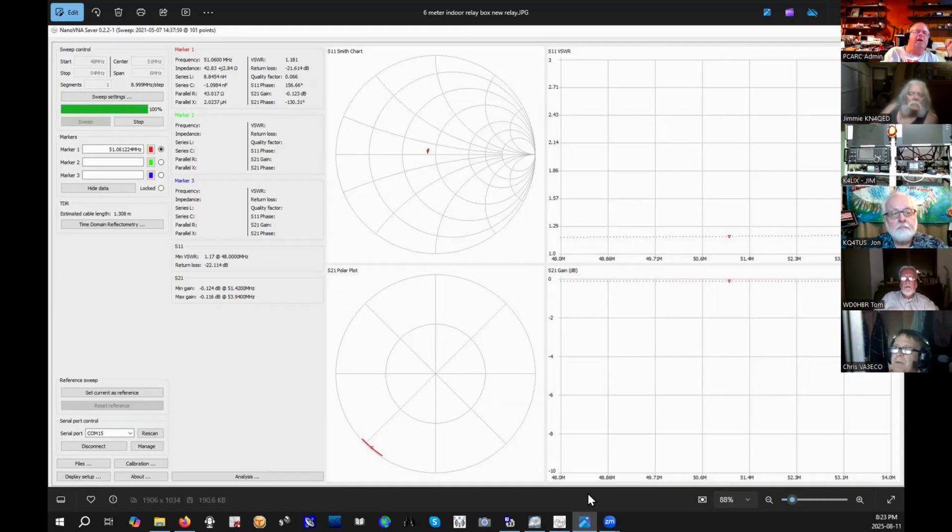No. Oh, it's looking at both ends at the same time? No. Well, you've got the analyzer and the coax, and the coax is hooked to the analyzer. There's just one port. It asks you to have an open circuit, and then it collects data, and then it asks for a short circuit, and it collects data. Okay. So that works. So this does essentially the same thing, but it's live. It actually measures the actual throughput instead of guessing based on the reading it's got.